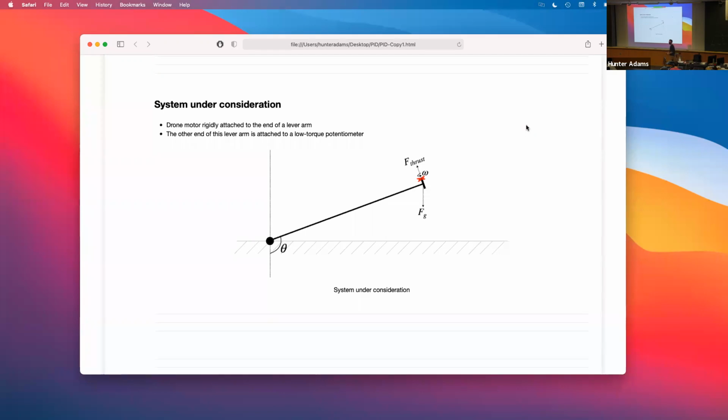The way a lot of you have discovered this is you've implemented some mechanism where you can increase the duty cycle to the motor, so you can increase its speed. And what many of you find is you can, by hand, push it up quite easily to about horizontal. And then as you move it past horizontal, boy, is it easy to just flip it over. One reason is the thrust out of the motor is proportional to the square of the voltage. So you increase your duty cycle a little bit, and you get a lot more thrust.